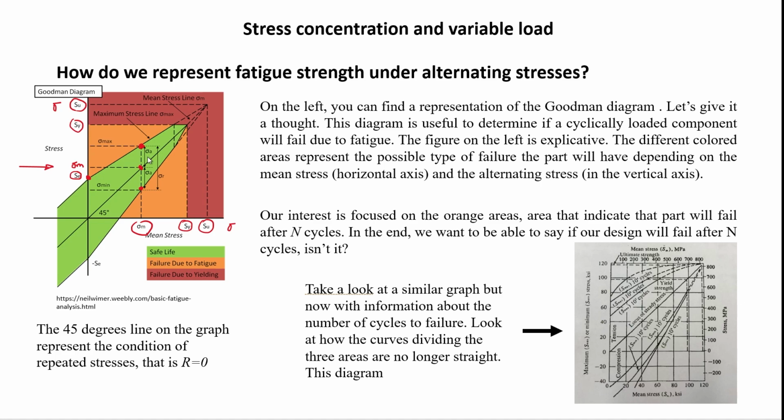If the loading case falls away from the yield strength and ultimate strength of the material, then you shouldn't be worried about fatigue either, because it's not going to fail because of fatigue. It's going to fail by either yielding or rupture, so you need to take care of that.